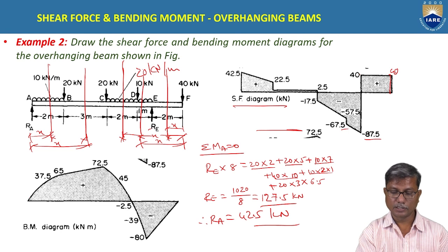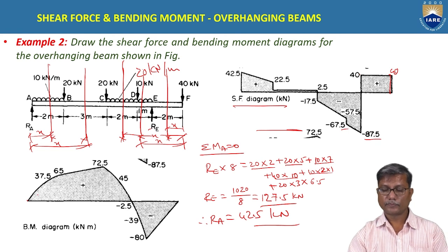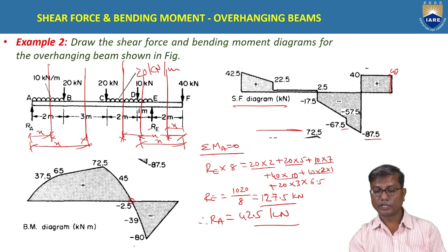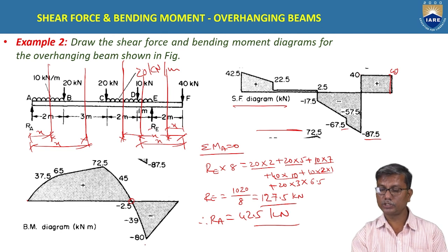Similarly, the bending moment diagram. You can locate this point of inflection by equating bending moment between D and C to 0.